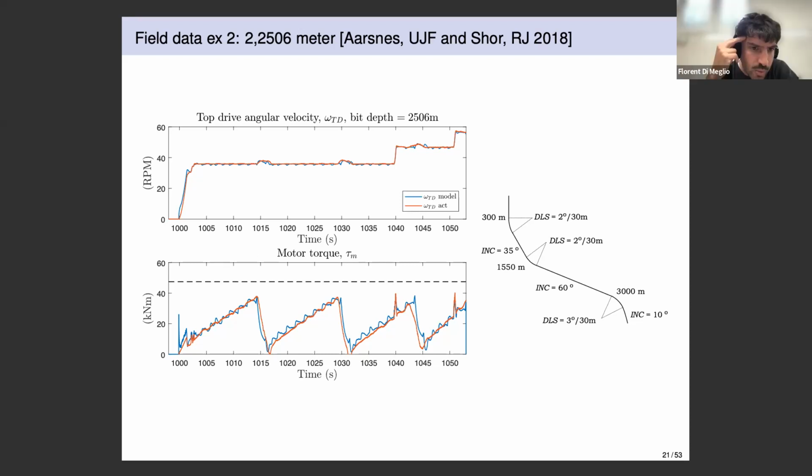That's an excellent question. I would say my guess is that we used a very, very low viscous damping coefficient for this, and so you completely neglect the damping along the drill string from just the drilling fluid typically, and I would say that's why all these high frequency things are still here when they don't show up in the sensor data. Okay. Yep.